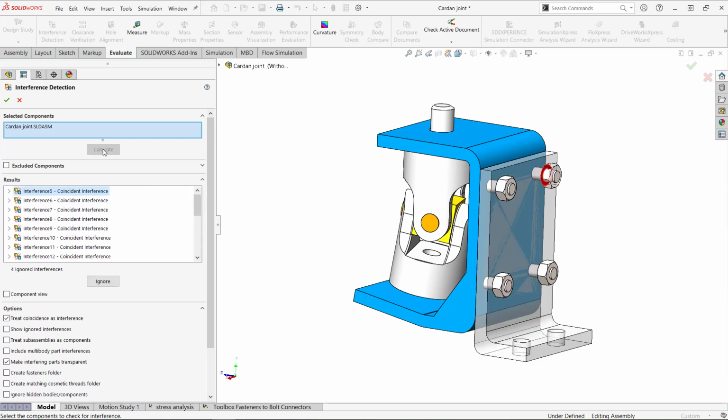This will detect how many face pairs are actually touching and are a potential for me to have to add context to when I'm doing a simulation study. In this case, I have 22 additional face pairs that I may need to go in and apply context to when I'm actually doing the study. This will give me an idea of how much time it may take for me to run through and vet this particular setup and get it done.